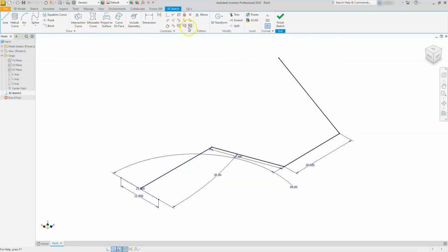So I'll select the line. I'm going to place it here. I'm still going to use the XZ plane. Drop it down. Let's go ahead and put our angle on. So using D as the shortcut, select here and here. Then I'll type in 45.